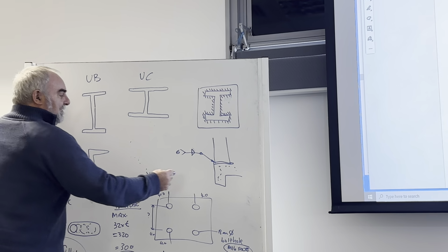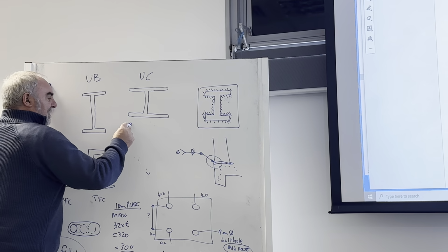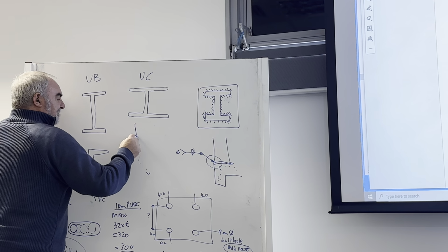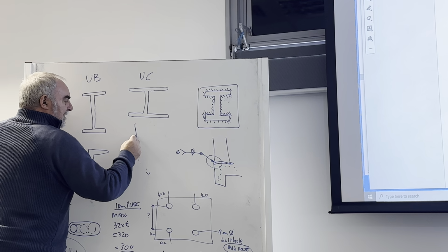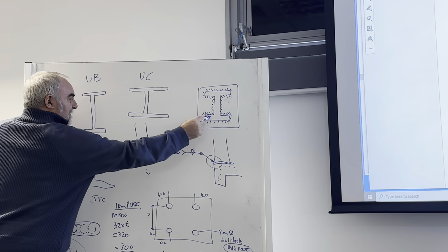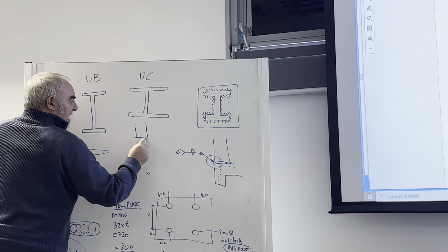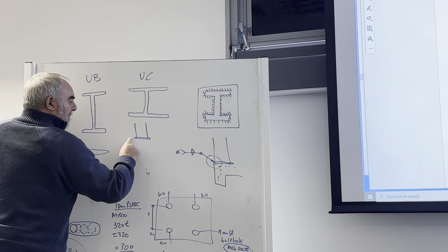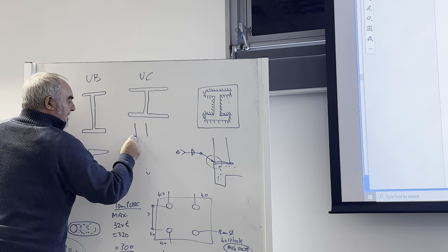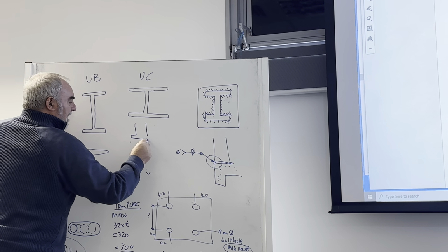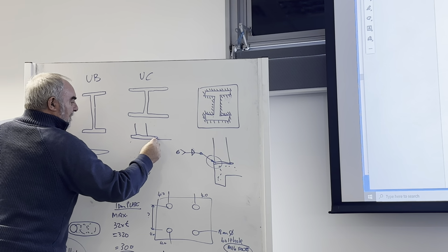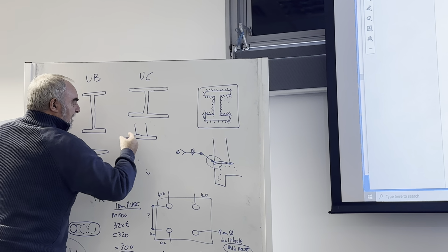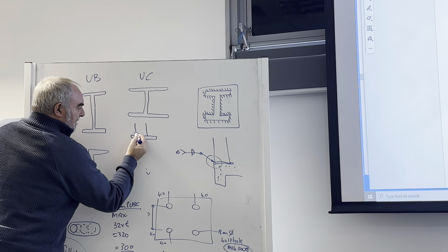Now if I was to zoom in on that, it would look something like this. There's your column coming down, which is this thing. The plate is welded to the bottom, and the weld on the plate would be a 6mm weld, would be this bit in here.